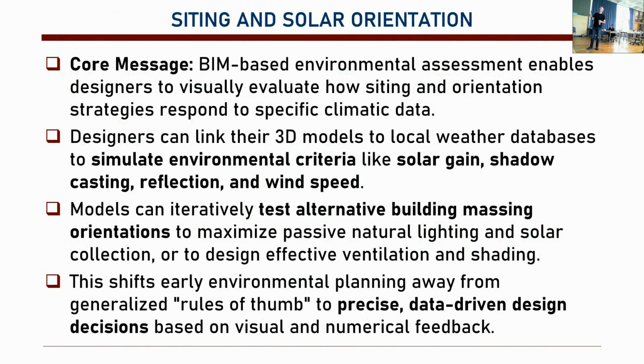Yeah, the siting in that regard. How does it work? With BIM, when we do the environmental assessment, we can figure out how the building sits on site and how its orientation impacts its performance. And we can simulate environmental criteria by using local weather databases.